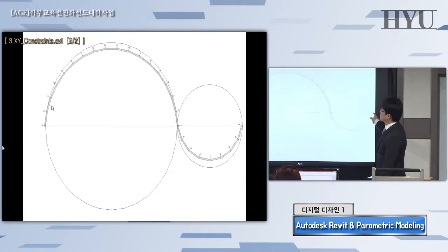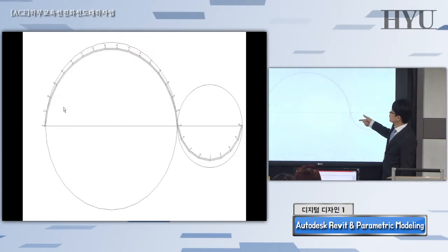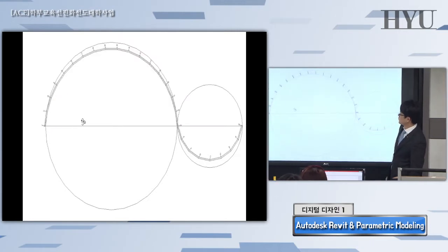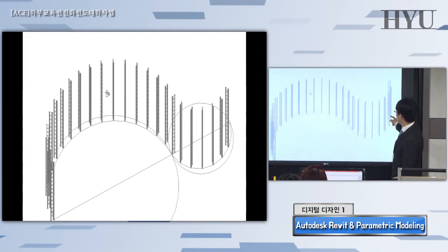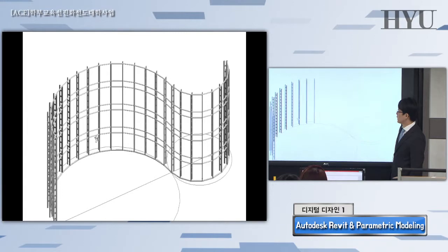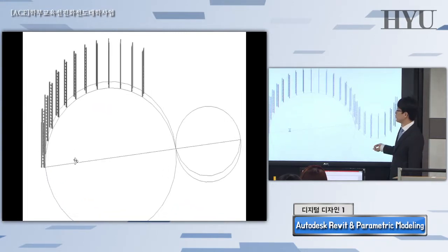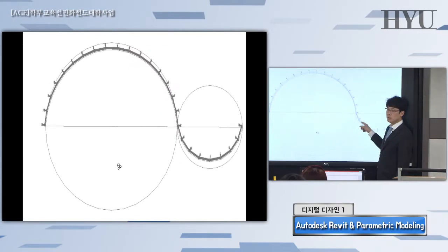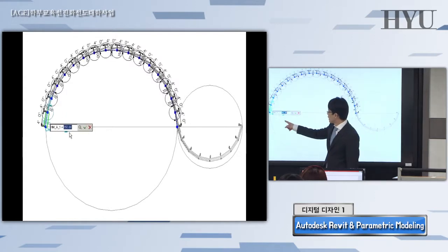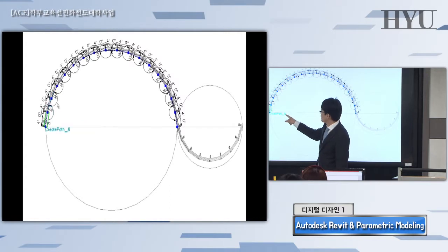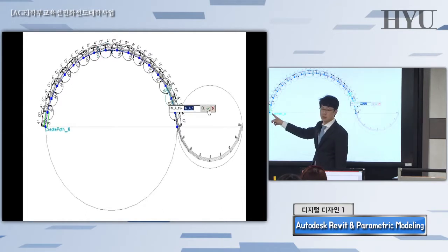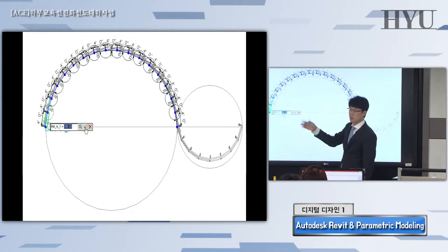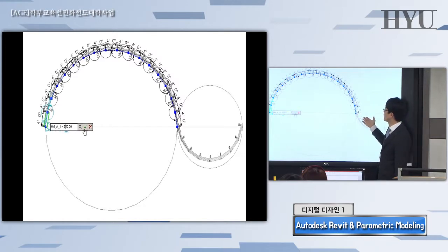The last example is a final product example. This is another section profile for making this one. This is a 3D object actually, so change the view, and the amount of vertical frames and horizontal bars are already installed. But what if you want to change the building surface, curve, angle, ratio, and so on? In that case, simply click the path, and the first angle is 350, and the other angles are currently parameters that are all the same as the first angle. Very simply defined. Of course, you can put even more complicated parameters.